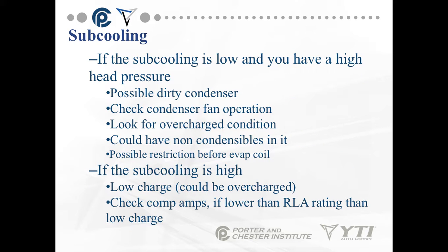If subcooling is low and you have high head pressure, you possibly have a dirty condenser. Check condenser fan operation. Look for overcharged conditions. Do you have non-condensables? Did somehow air get into the system? Nitrogen left over from the last time the system was pressure checked. Or you possibly have a restriction before the evaporator coil.